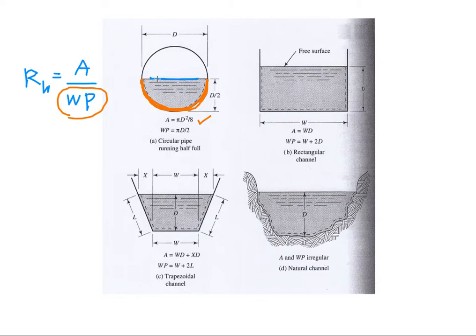This area cannot be calculated as wetted perimeter because here we have liquid and gas interaction. Liquid and gas interaction will not give a no-slip condition, as we know from the maximum velocity contour just now. We found that there is no no-slip condition here, so the water is still moving on the surface. That's why we cannot count this area as wetted perimeter.